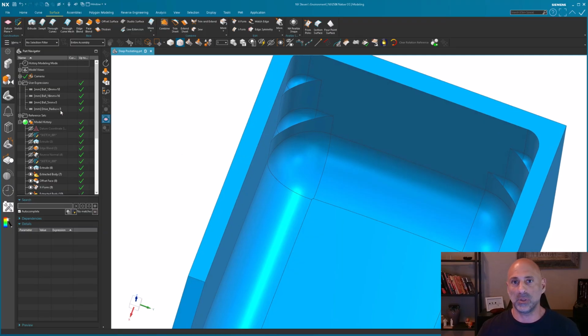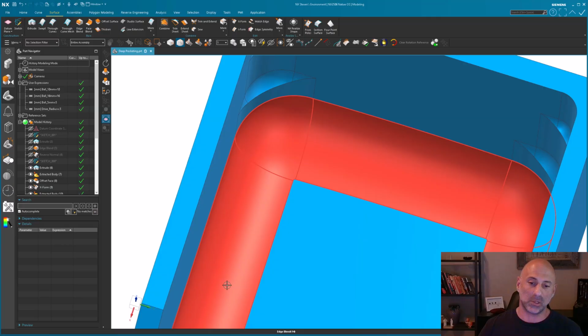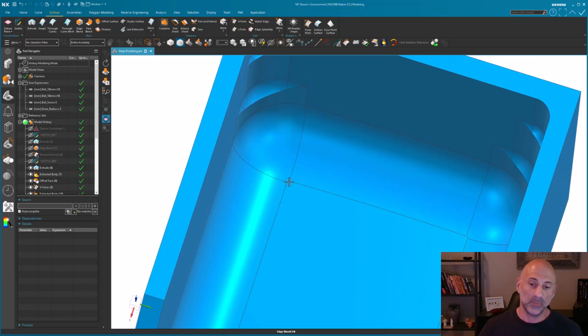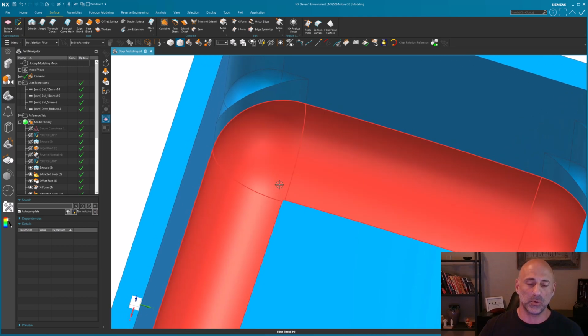You may want to add 1 millimeter. And what that does is, as the cutter comes around, it doesn't come to a sharp point right over here. It drives around that corner. Because if it comes to a point, there's a dwell. There's a moment where the machine's cutting in and then changing directions. So there's a potential for an undercut.